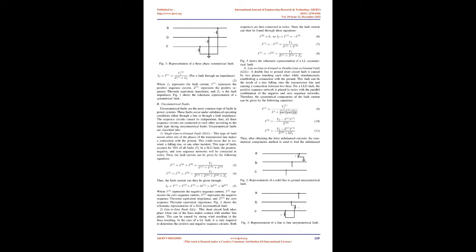Lack of safety measures. Many of the electrical equipment which are part of the power system may cause short-circuit faults due to malfunctioning, aging, or having internal failures. Thus, if fuses and circuit breakers are not up to par with what the facility requires, then these faults will occur. Therefore, safety measures should be checked regularly so that they are evaluated to determine if they can handle a fault if it occurs. Effects of short-circuit faults.